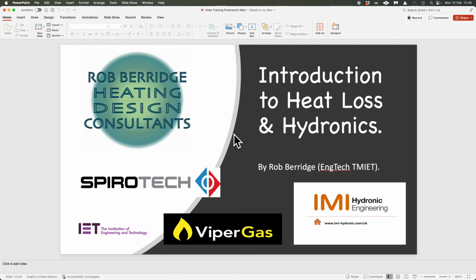I did a video a couple of weeks ago on kilowatt hours to kilowatts, where you can take a gas bill and input all the kilowatt hours that you've had for the worst month of the year. You then take energy divided by time, so you divide that by the time of heating in a monthly cycle, and that will give you a kilowatt rating of what you need. Obviously, you've got to take things like cooking, if you're cooking with gas, off of those figures.